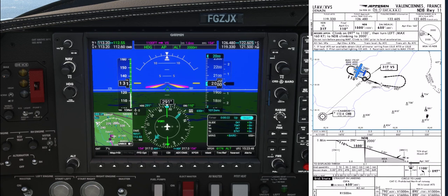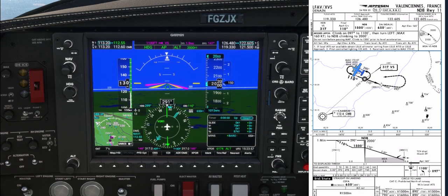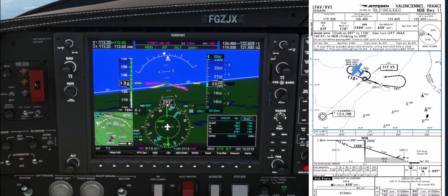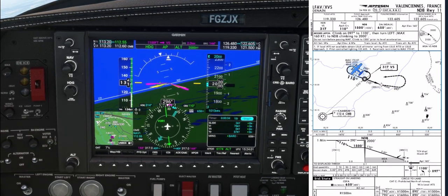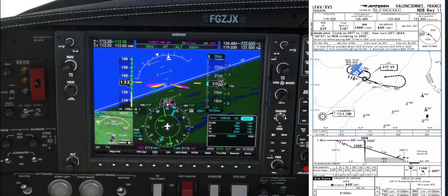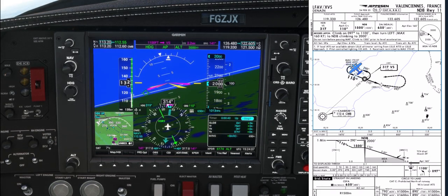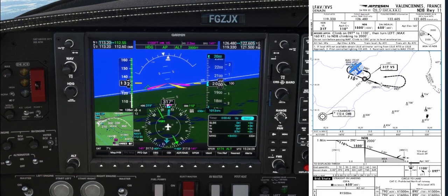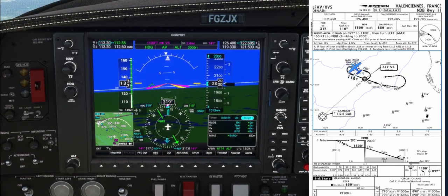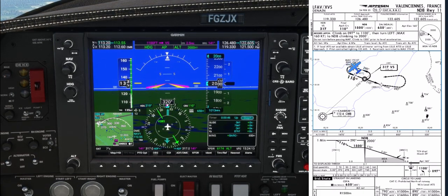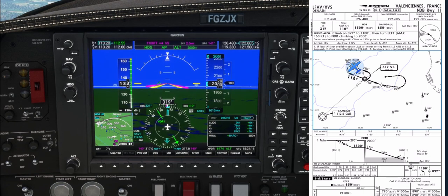36 seconds. So at 36 seconds, we should have a relative bearing of 220 degrees, or 40 degrees to the tail of the needle, and we should be on the teardrop, relative bearing of 210 degrees, 30 degrees to the tail, at 54 seconds. If not, we apply the correction depicted in the holding module. We were too early at the bearing 220 degrees, 40 degrees to the tail, so we turn to the needle to follow the teardrop until the end of the outbound time to correct our position.